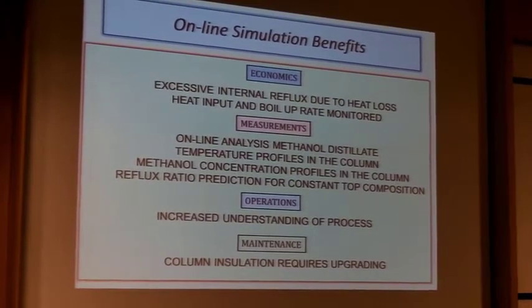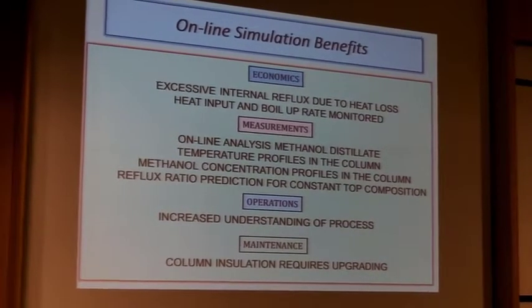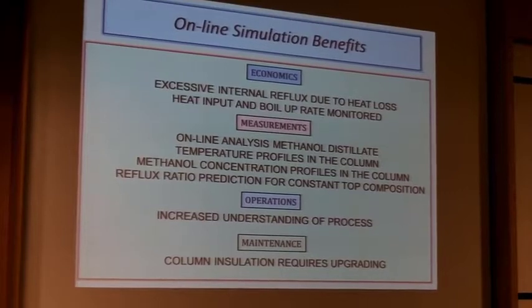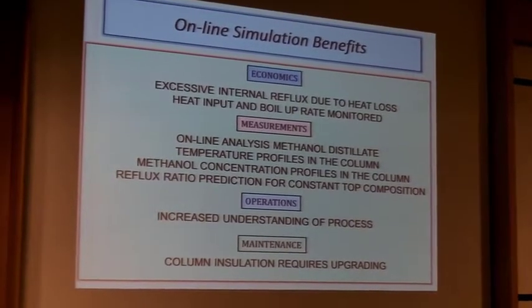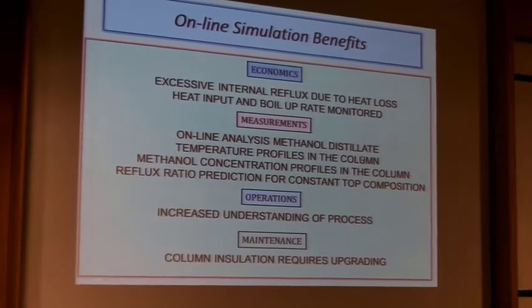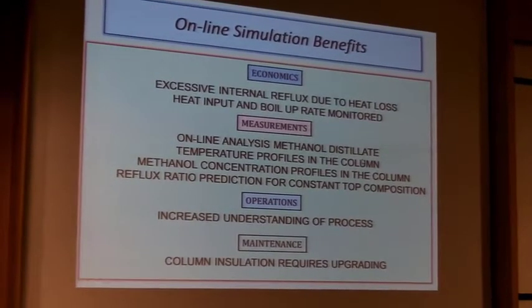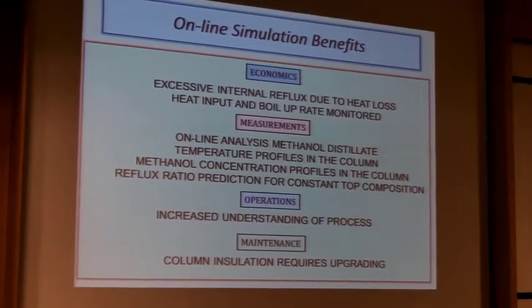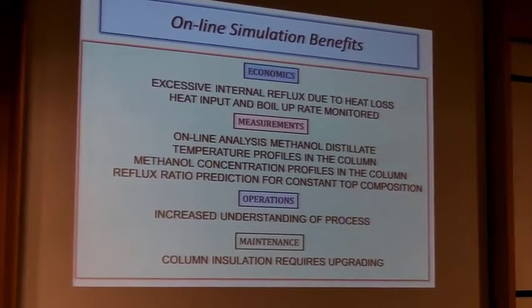We could actually, the thing about the simulation is you can monitor variables that you're not necessarily measuring. So now you don't have to measure everything. For example, we could do an online analysis of the methanol distillate concentration based on the simulation values. We didn't have to measure it online.